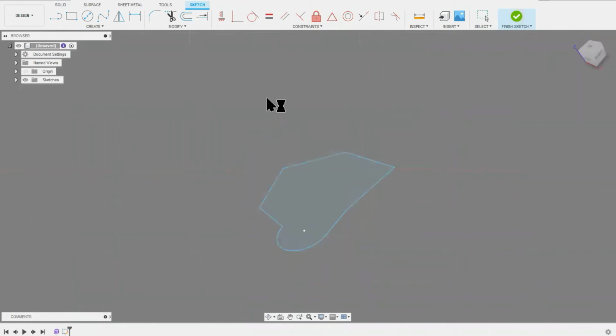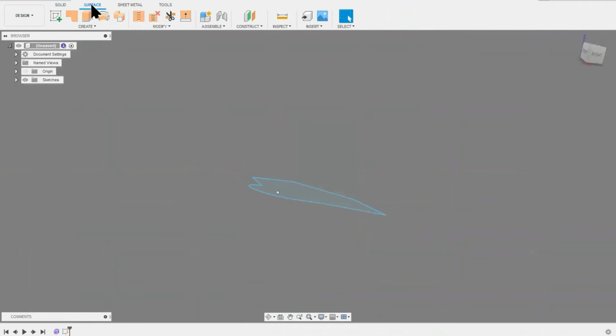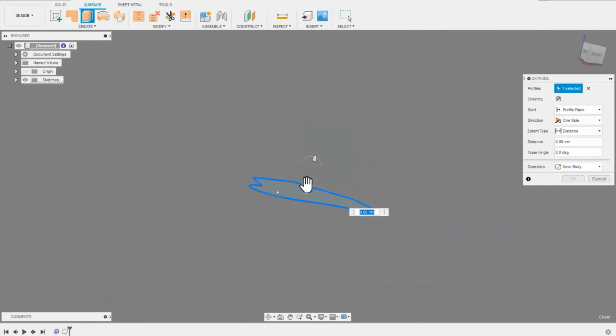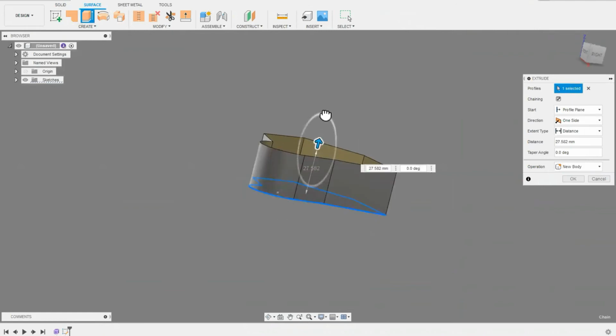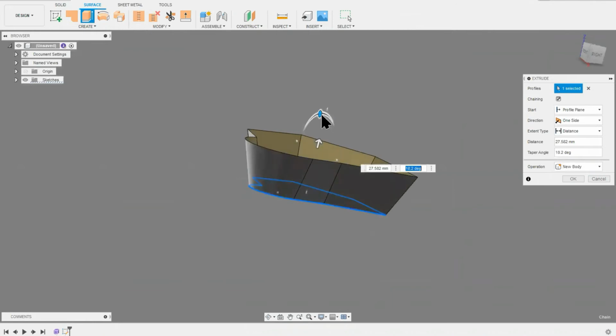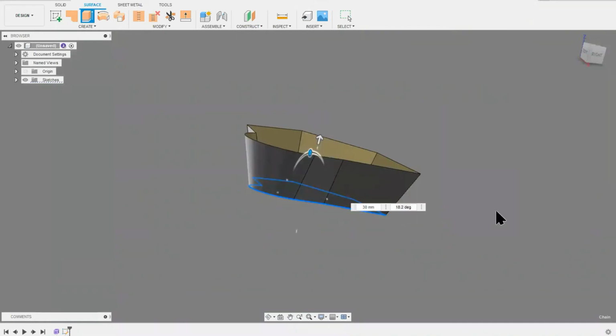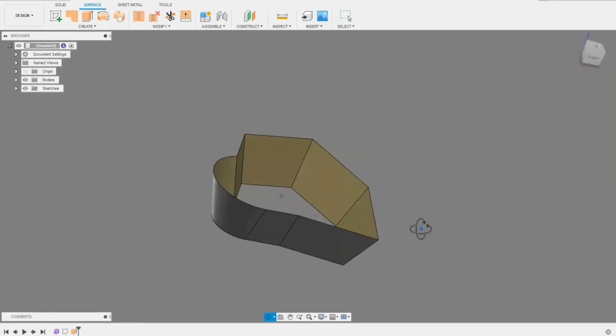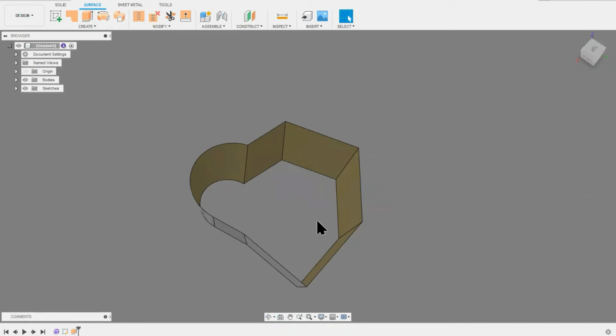And effectively, I can go into the surface mode and do a very similar thing by extruding a shape as a surface. And again, I can still add taper to that surface, okay? Here we can add the depth value for that particular surface and pick OK. So this is a surface model, and as you can see here, it's a completely hollow model.